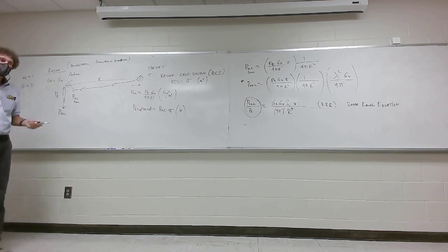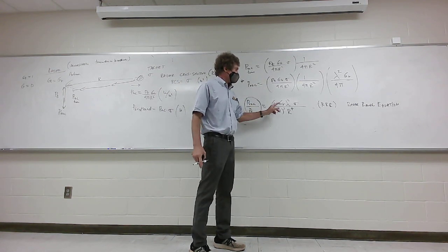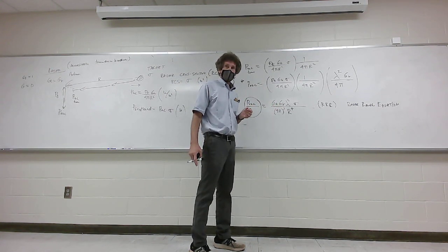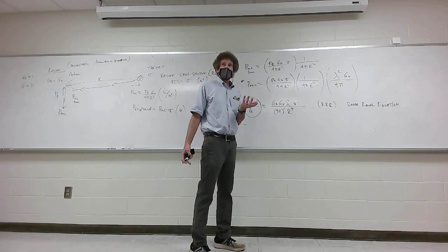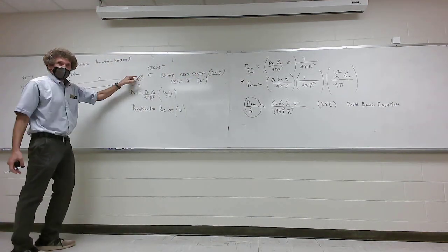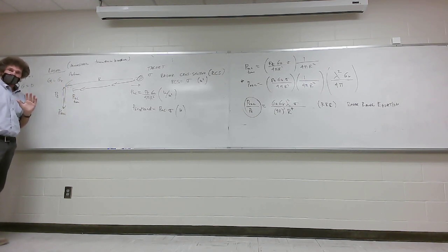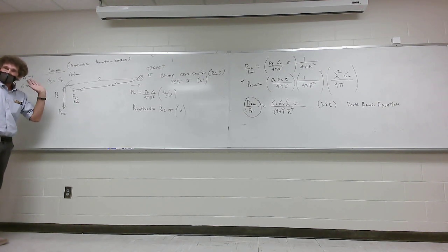But you can obviously see, if we have dipole antennas, say they're half-wave dipoles, those would be 1.64. With me? You got the frequency, you got lambda. You can figure, if I give you a target size at a given range, you can figure this ratio out. If I give you the amount of transmitted power, you can figure out the received power. You follow me? So it's something that makes sense, but you should know how to get the power density here, total reflected power, power density here, and total received power, all as separate things, all right? Just make sure you know how to do that. And if you've been studying along and know Friis, then this should make sense.